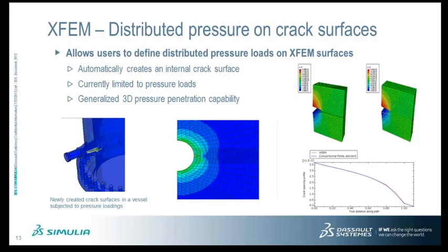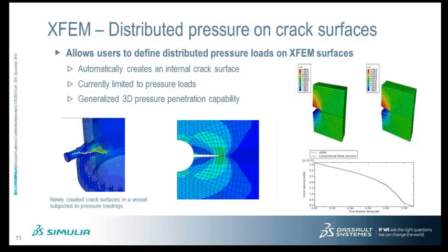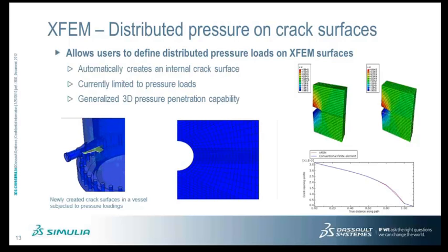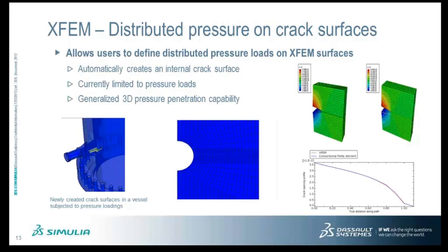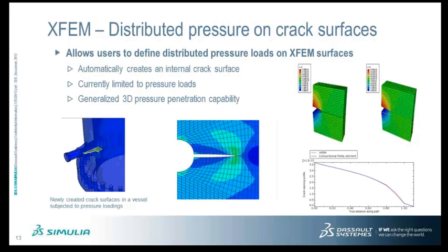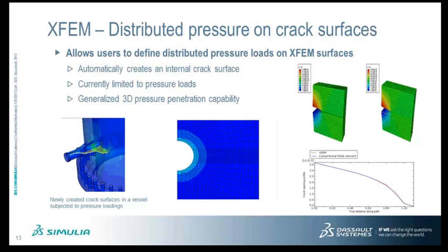So in case you don't know, XFEM is a technique by which you can model fracture through a model where the fracture does not have to follow one of the element boundaries. One of the advantages of XFEM is you do not require that the crack conform to the mesh.